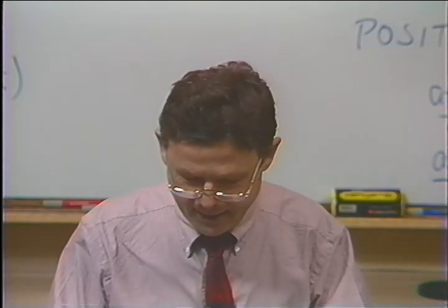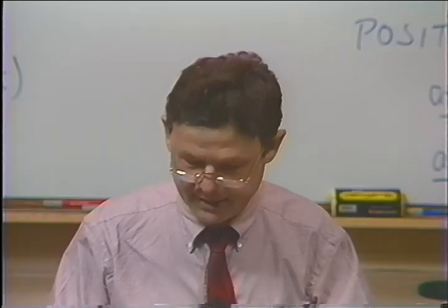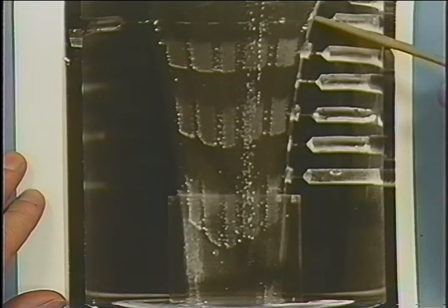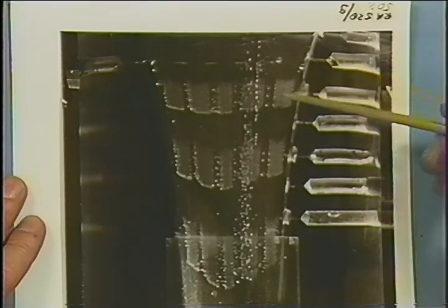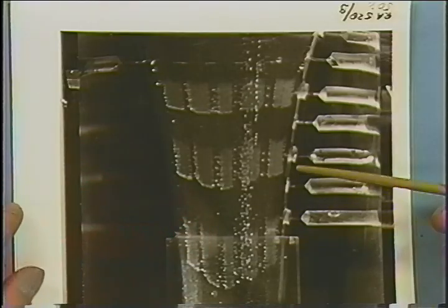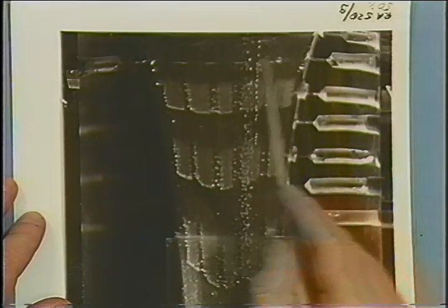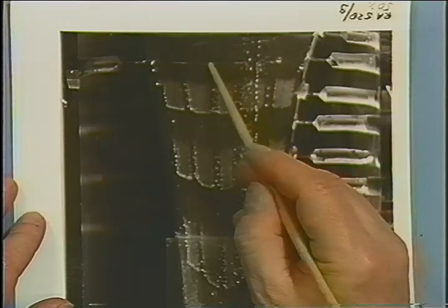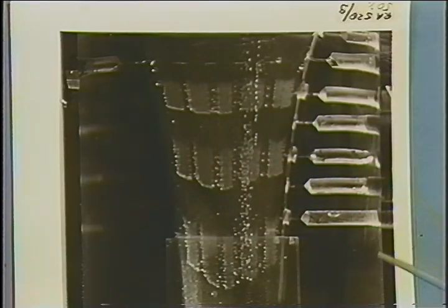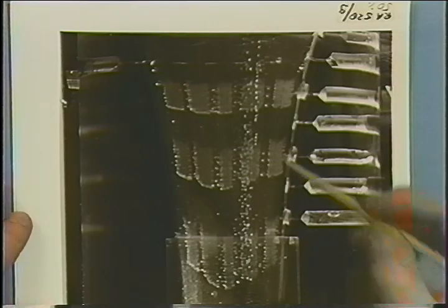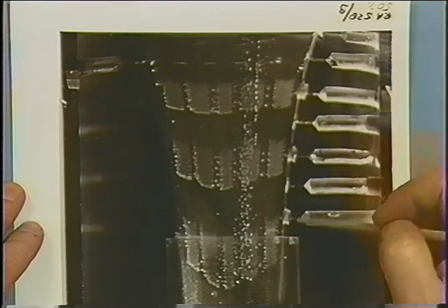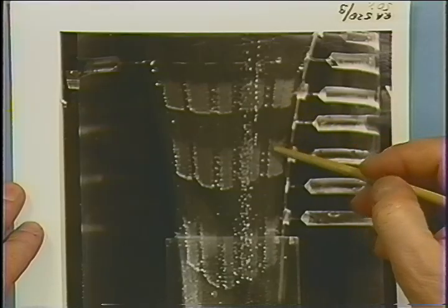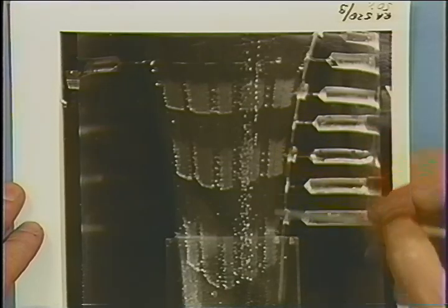You saw a picture of that early on when we talked about kinematics. This is the converging die section of the schematic, which you saw before. So liquid is moving downward and it's accelerating as the diameter is decreasing. We have a wire across here which has some bare spots, and then by occasionally putting a pulse of current in there, we produce bursts of bubbles which have some rectangular format here, and as these bubbles move down with the acceleration, this burst is being stretched longer and longer.